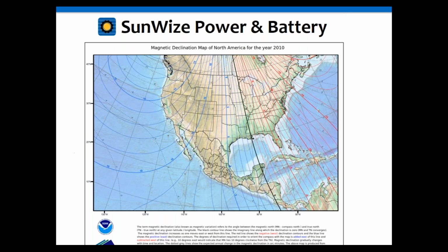Basically what that means is, here's a declination map of the United States. What it means is that magnetic south isn't true south. There's a slight deviation that is constantly adjusting, by the way. It can adjust by about half a degree per year, so these maps are constantly updated. This one's actually from 2010. It's probably already outdated by about 3 or 4 degrees because of that shift.